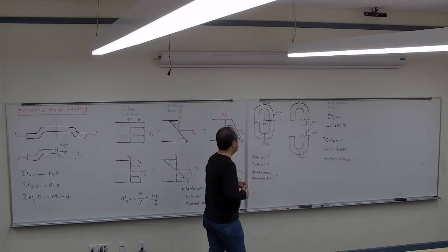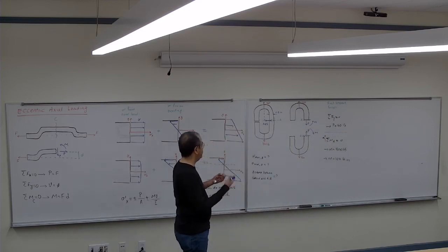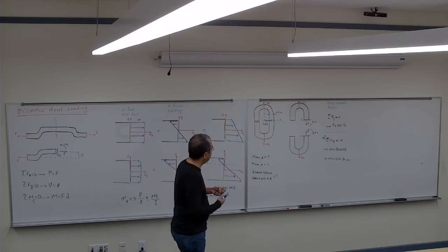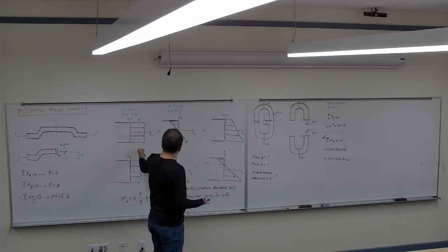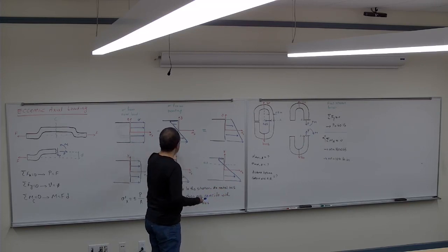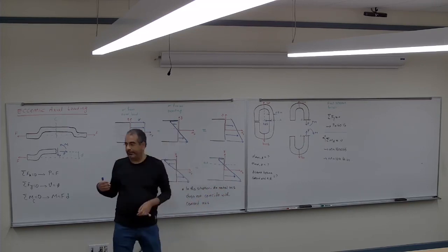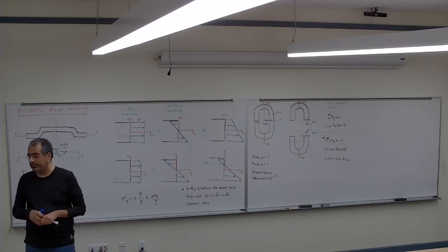So now I have the internal forces: I have the tension force, the axial force, and the bending moment. I have to calculate the stress for each of them separately, and then eventually add them together.